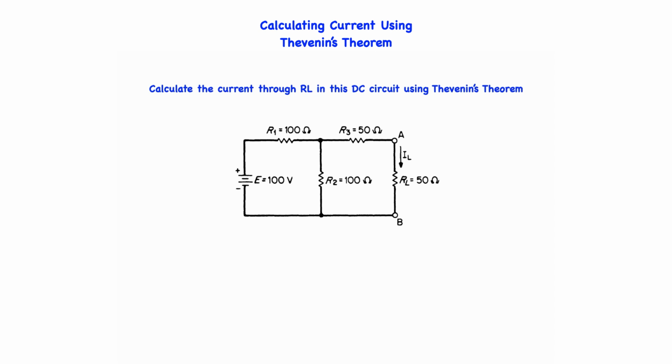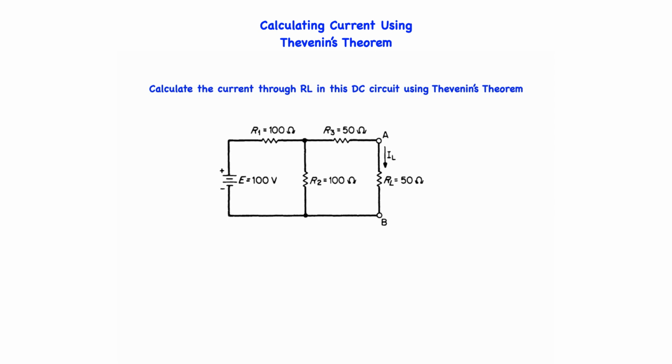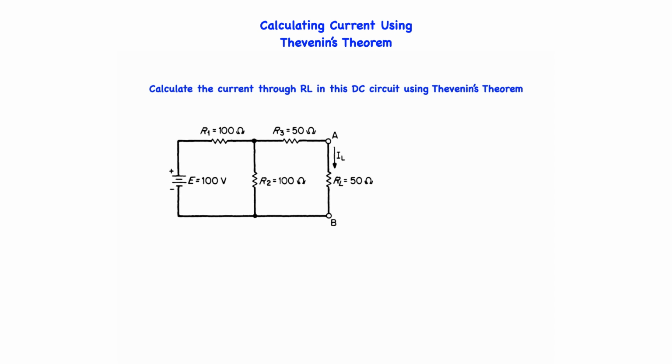When the Thevenin equivalent circuit is determined for a network, the process is known as Thevenizing. When Thevenizing the circuit to find Thevenin's voltage ETH, the load resistor is removed. The open circuit terminal voltage of the network is calculated. This value is ETH.